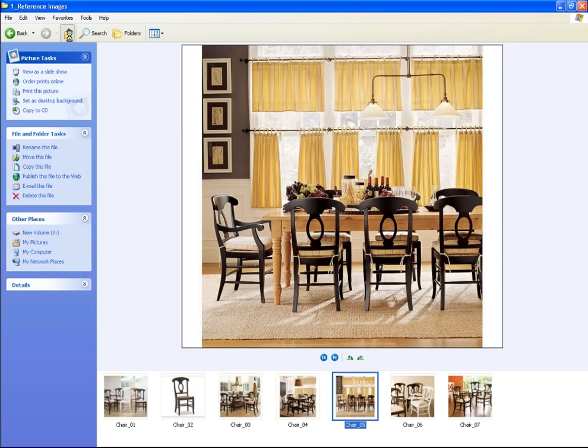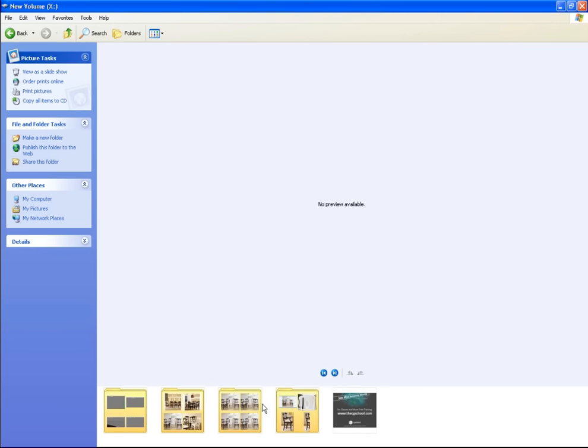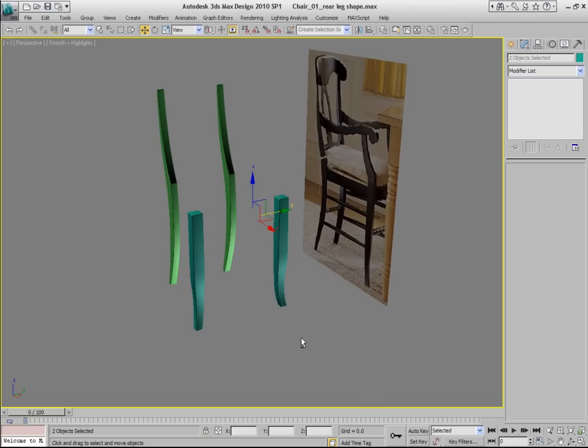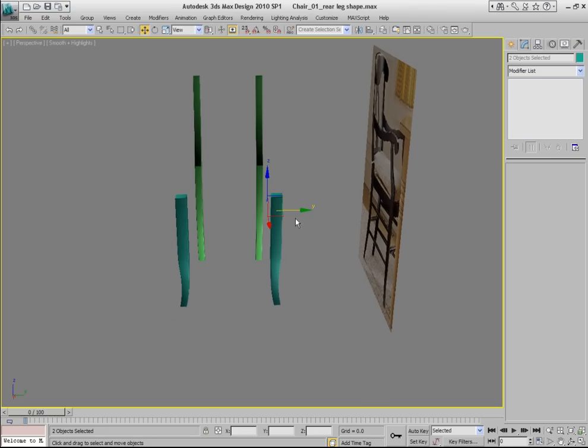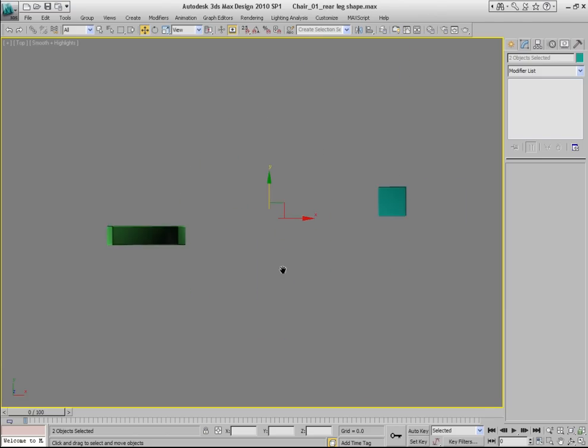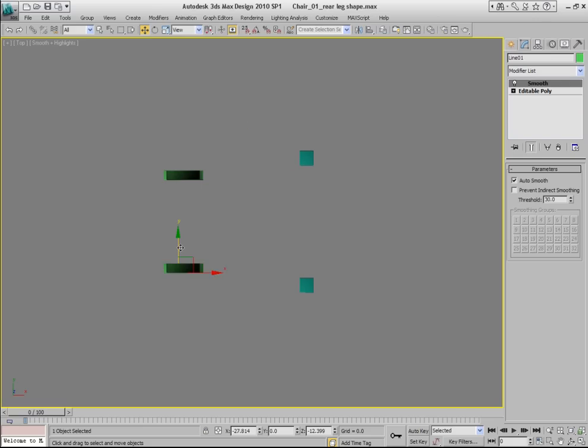And let me show you this other illustration that I prepared before this webinar for your convenience. You can see this, the distance A is equal to the distance B, and just using this information, do the same thing here in 3ds Max. Just move these guys one from another along y-axis until you see that the distance between the outer edges of the front legs is equally the same as the height of the front leg itself. So now when we've spaced the front legs, just go to top view and space these rear legs.